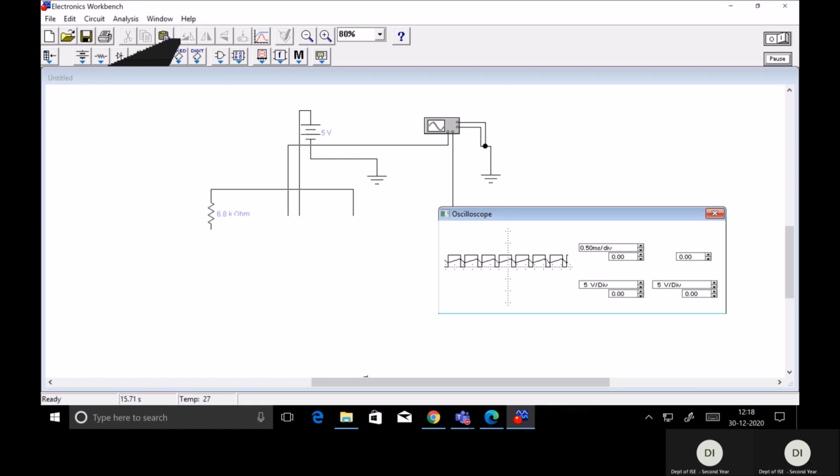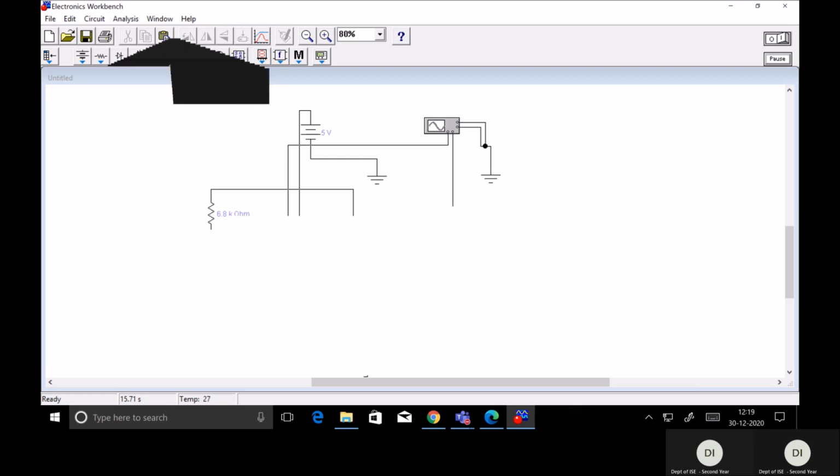The capacitor waveform, when you observe in this circuit, is in the form of sawtooth. So this is how we need to get the waveform for 555 timer IC for the duty cycle greater than 50%. Here I have constructed the circuit for 75% duty cycle.